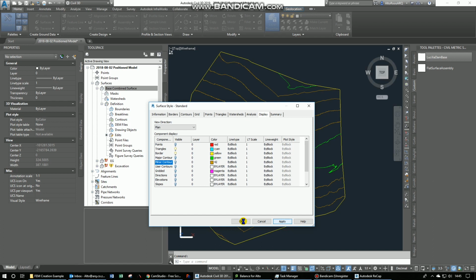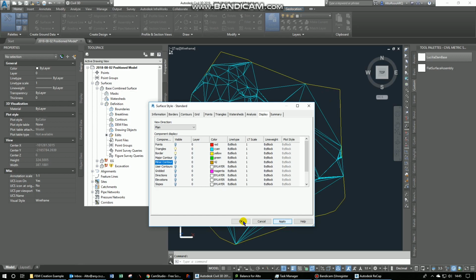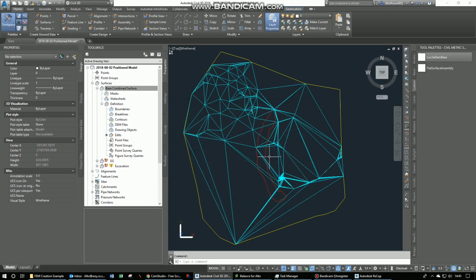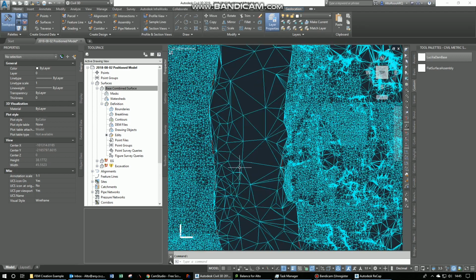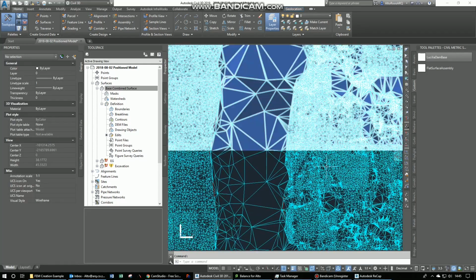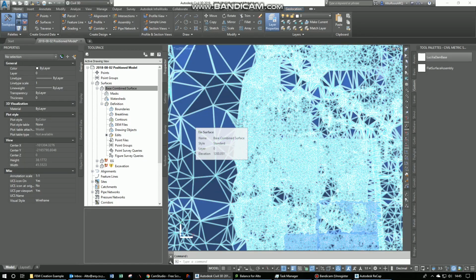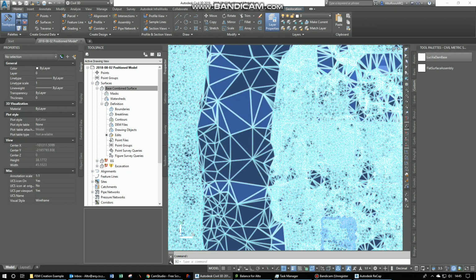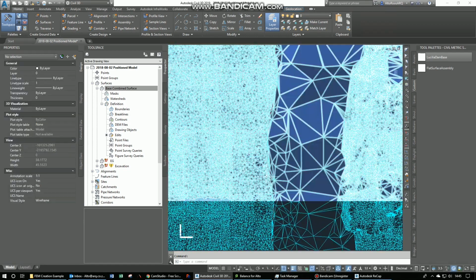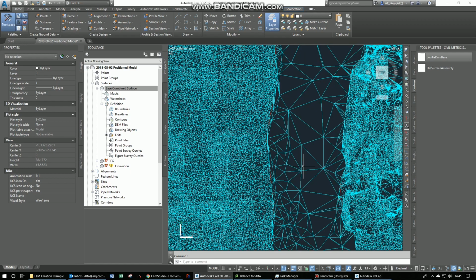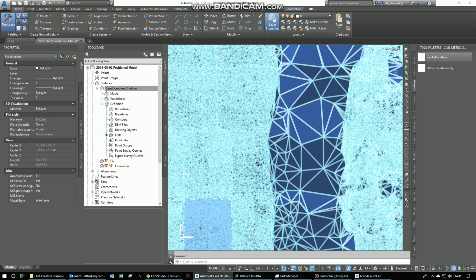So we must convert this into a more user-friendly model. The way we're going to do that is by creating a bunch of point groups at different grid spacings, and then we'll paste those on top of the surface to get new or refined data that'll be used as an input for creation of the big surface.